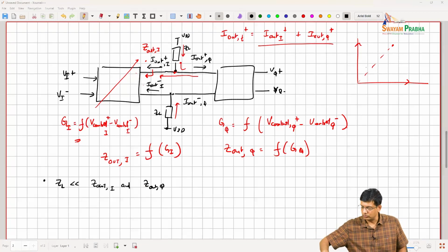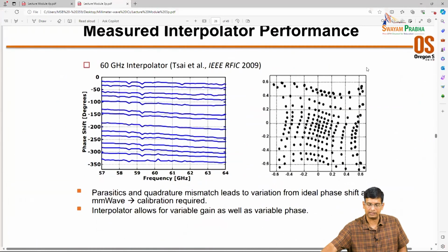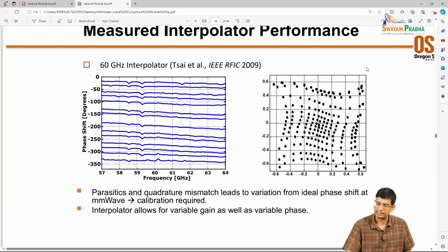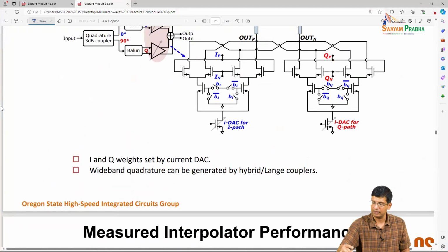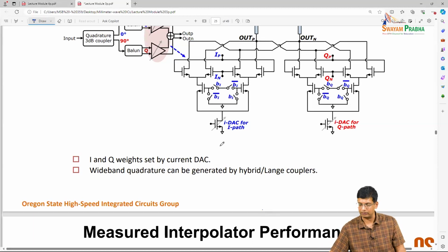So for example, this is an early result with these kinds of approaches, but you can see what I'm talking about. Ideally you would see all these points on an exact constellation plot here, right? Your constellation should look rectangular, because that means that the I and Q weights are adding independent of each other.